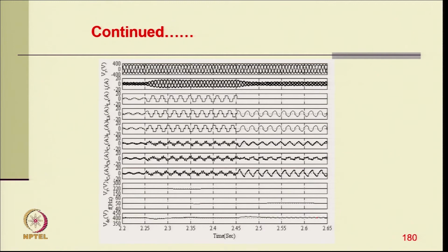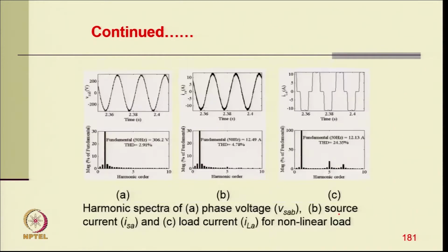Then this is subjected to a 3 phase nonlinear load. You can see here a 3 phase nonlinear load at a lower value, then an increased load, then one phase load is removed. So load balancing, harmonic elimination and change of load are applied to this system, but the generator currents are balanced and sinusoidal, and the compensator is providing harmonic elimination and load balancing. Apart from that, it regulates the terminal voltage to a constant value, with the DC link voltage also regulated.